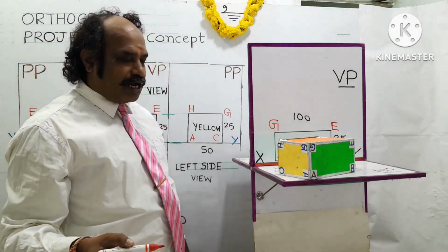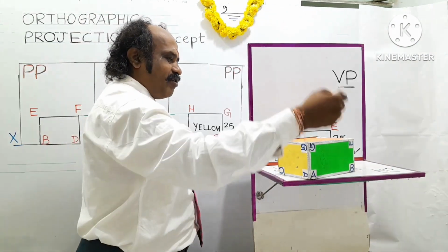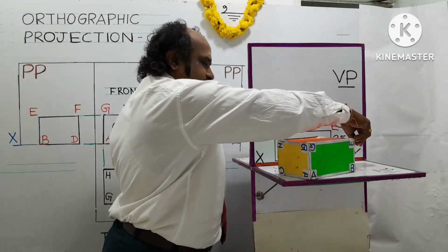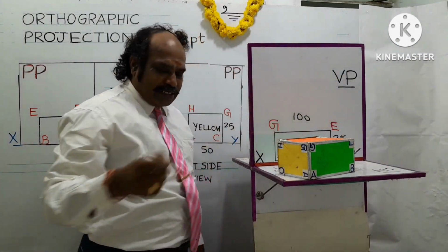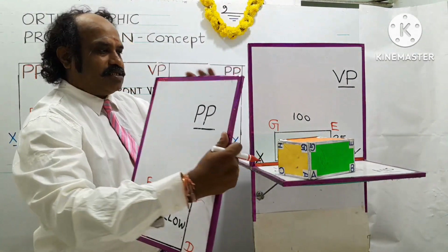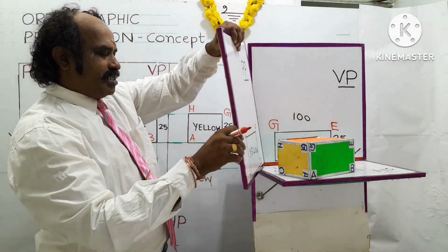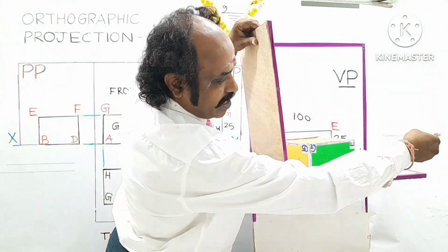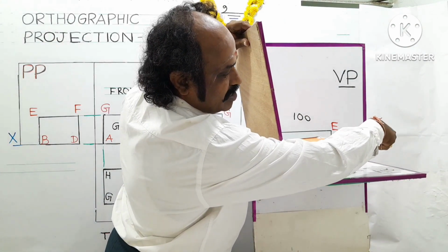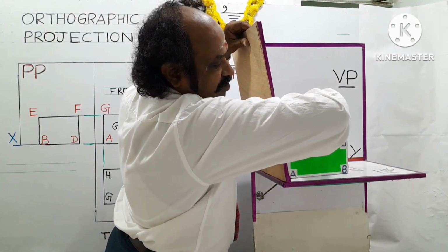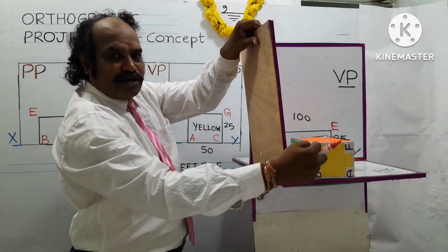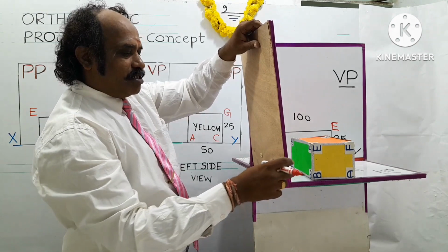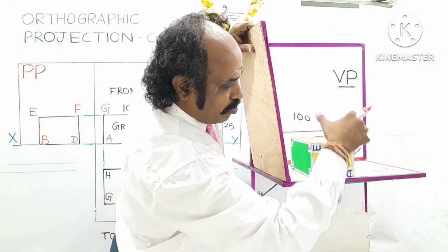And now I'm going to explain how the side view is called a right side view. For this arrowhead direction of the front view, this is the right side. So for projecting the right side view, I'm going to place the profile plane on the left side of the object, like this. Looking in this direction, called the right side direction, the observer can see this yellow surface. This yellow surface as a smaller rectangle is projected on the profile plane placed on the left side of the object. Like a ray, these points are projected.